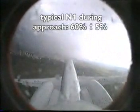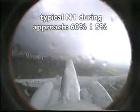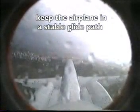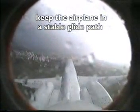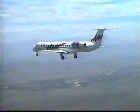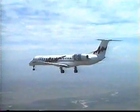In the Embraer regional jets, a typical target N1 is 60%. And if you keep it within plus or minus 5%, it will be good. Keep the airplane in a stable glide path. And remember that large changes in airspeed will require also proportionally large changes in power and attitude. Variations in the target airspeed must be kept within a range of 5 knots.